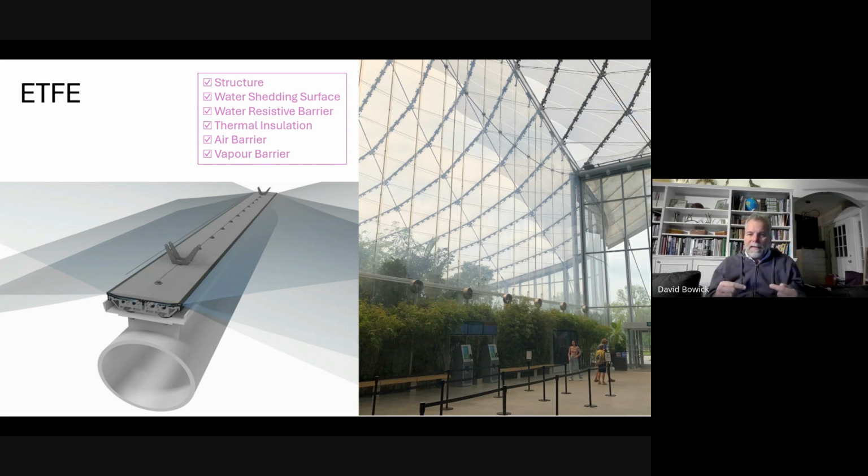The water will get in there. In this particular example, you can see that the extrusion sits in a steel trough. The idea there is that the water gets into the extrusion, drains through the extrusion onto this little steel channel, and is directed out of the building. But it has to be a drained joint.